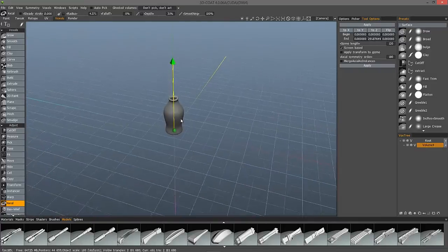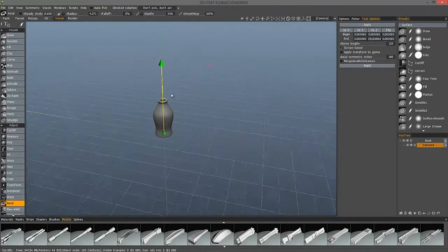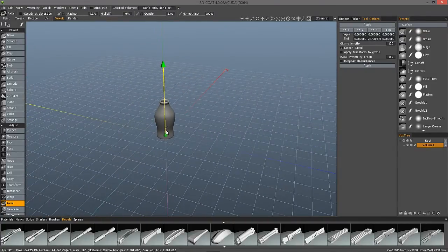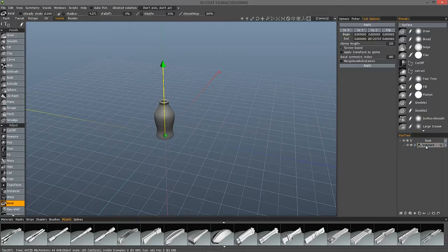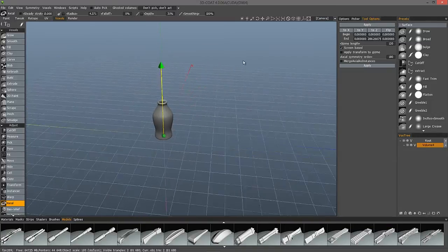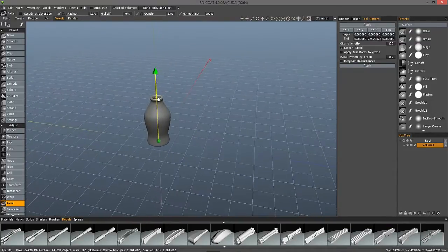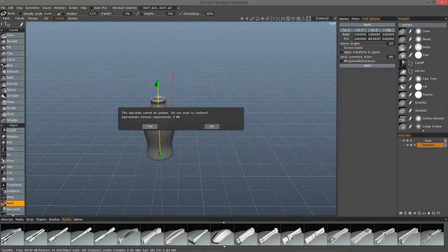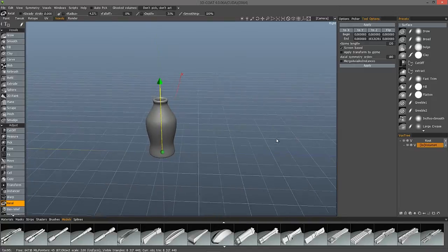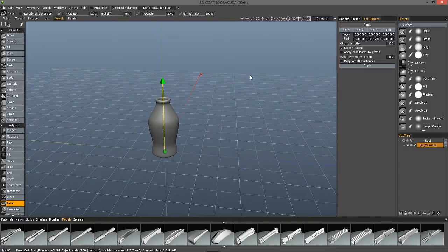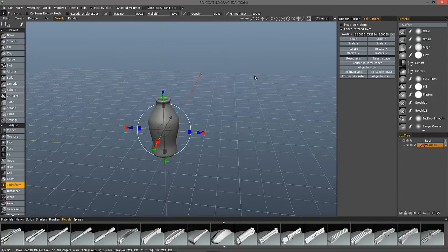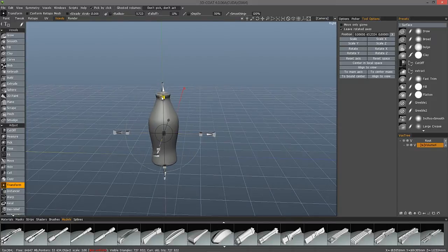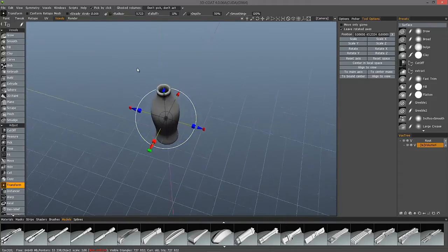Okay, and depending on the size of the object on the grid, if it's small on the grid, you're going to need to increase the resolution on your layer before you apply it. That way it keeps all the creases or edges and so on. It's not too rough. In this case, I'll give it 1 level of resolution and click apply. I can scale it and so on.